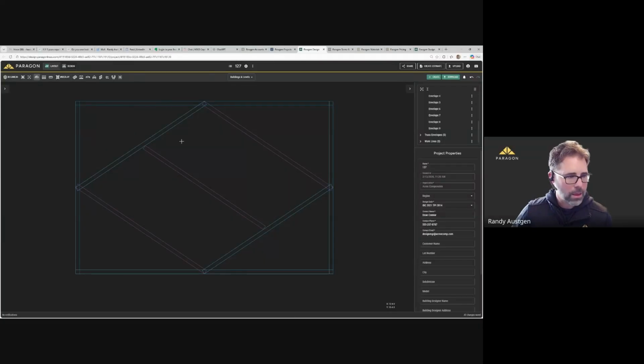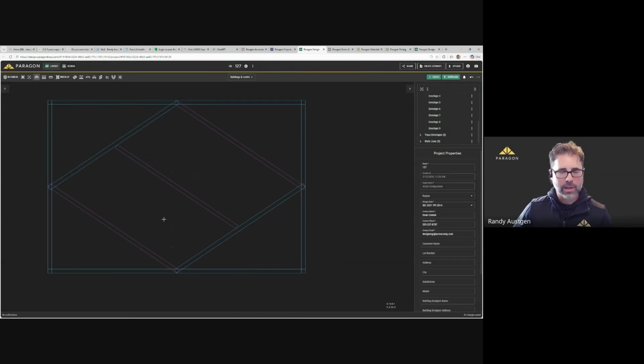So when it comes to wall justification or bearing justification, with current functionality as it is today, when you start creating your bearings, it's always going to start at that 0 point, and as I found, it's best or optimal to work in that counterclockwise fashion in order to have your wall justification where you want it when it comes to dropping in your roof and ceiling planes.